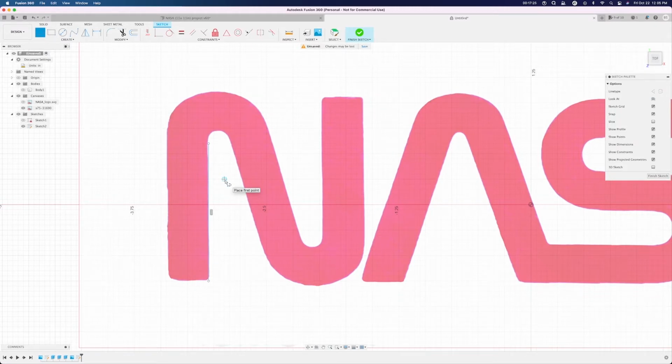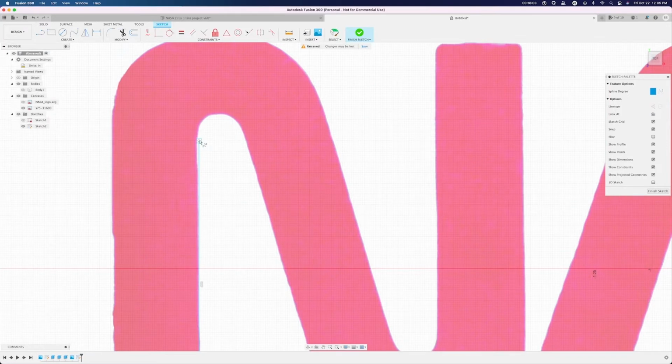From here, we'll switch to the control point spline tool. In order to do that, you can press S on your keyboard and type in control. And then you should automatically have control point spline. Click on that, and it should open the tool for making the control point spline. From here, you'll just want to draw around these curves right here, and I'm going to start from the end of our line previously. So I'm going to select that, draw another, and just keep clicking around the edges until it kind of matches evenly.